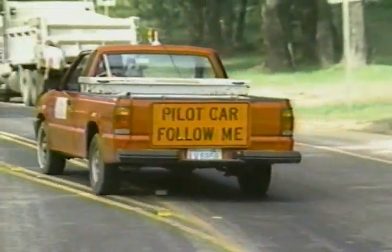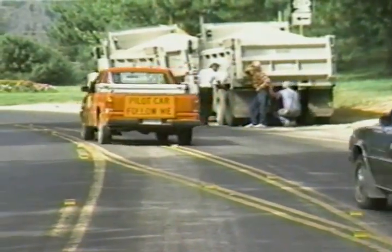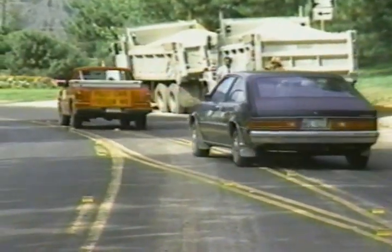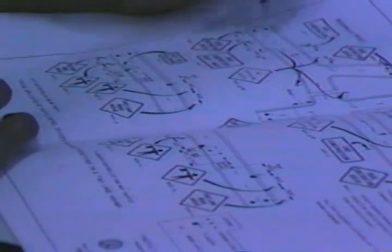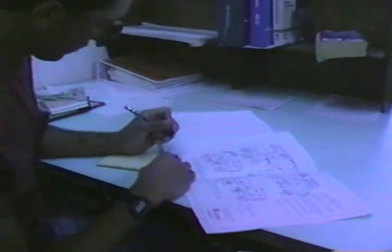To further protect motorists and the new chip seal, pilot cars may be needed on projects constructed under traffic. So carefully review the traffic control plan. Make sure it's approved and see that it's followed throughout construction.